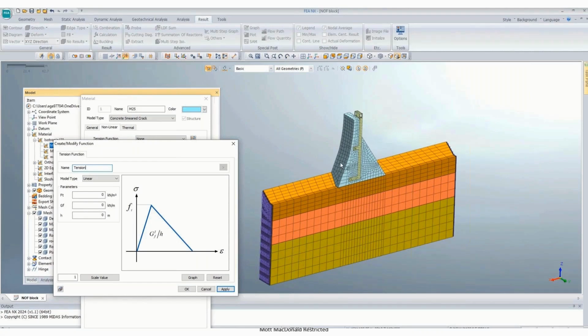As I told you in the previous session also, the tensile strength of concrete you can consider as fck by 40. Say for M25 concrete, you can consider about 0.6 MPa for the plain concrete, without considering any reinforcement.